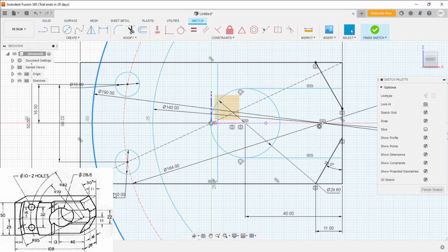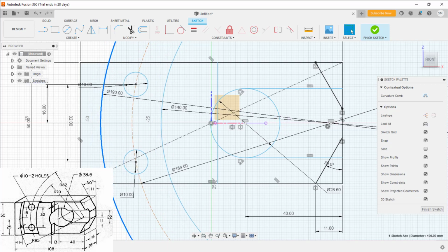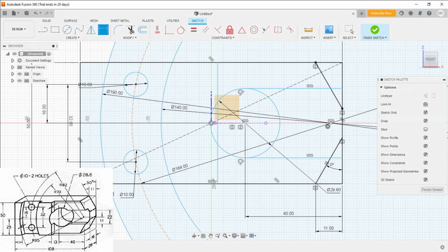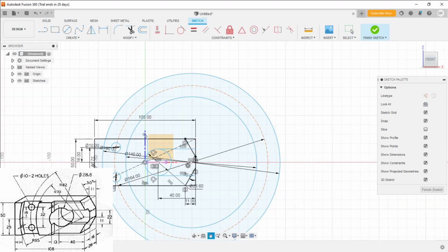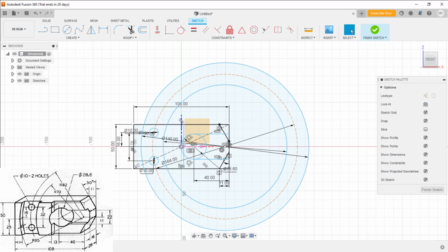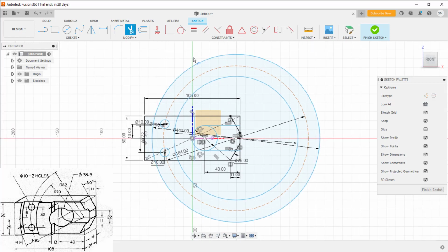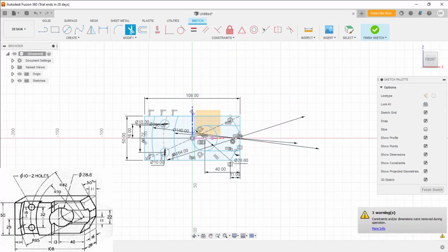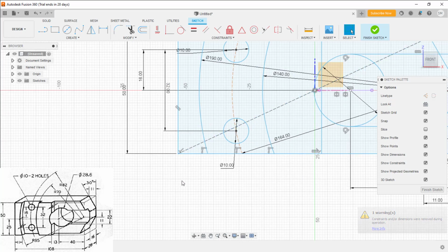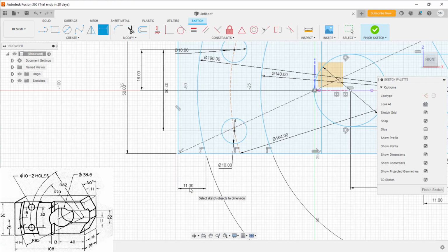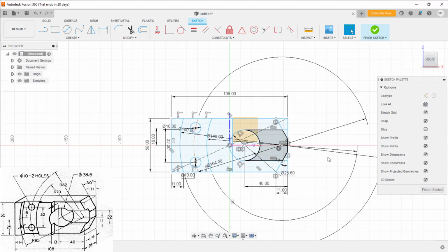So again, try moving it. It is moving. I need to define the distance from this left corner edge to the leftmost arc. For that, you cannot directly define, so you trim these things outside, which is not needed actually. T is the shortcut. Done. So zoom in now. Now you can define it. D shortcut, dimension from here to here, it is 11 given. Right, now try moving it.